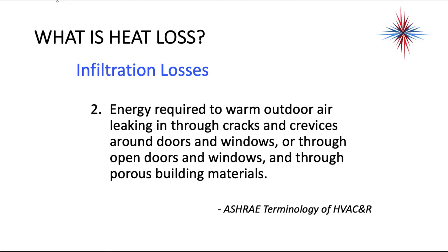Infiltration loss is a little bit different. Infiltration losses is basically energy required to warm outdoor air leaking in through cracks, crevices around doors and windows, or through open doors and windows and through other porous building materials. Okay, so infiltration loss has to do with breezes blowing through cracks and crevices. Anything that's a porous material. You can feel infiltration losses most often because it will feel like air moving.